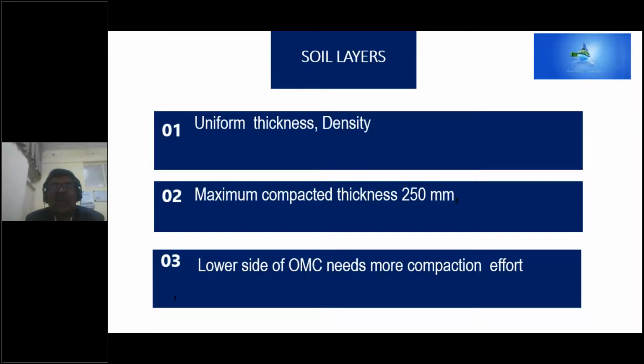OMC plays a vital role. If we are not at OMC, then we may not achieve the maximum density, and that results in all these implications and complications, whatever we discussed so far. So maintaining OMC is very, very important, so that we achieve the maximum density possible, so that we can optimize the materials, optimize the design, and even get better performance.